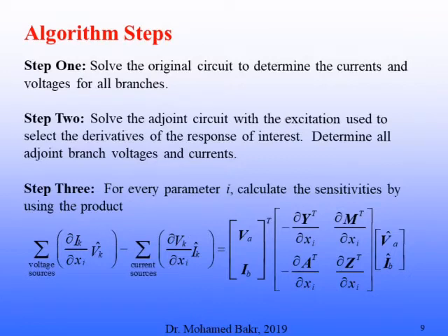Notice one word of warning: these matrices are complex, because in general this is AC analysis. So you have to realize that these are not real matrices. They could be complex matrices if you have capacitors and inductors and so on.